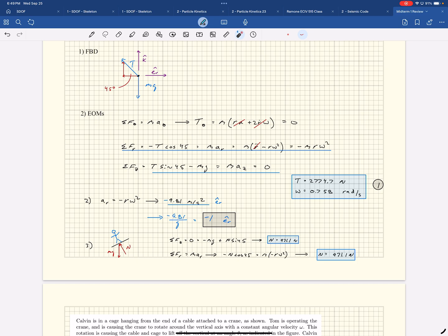We'll look afterwards. It is because of gravity. It's weird because gravity is an acceleration, right? But we don't really ever talk about it being an acceleration. We're putting it on the force side of the equation, so it's applying a force. So really, in this particular case, unless you let go of it and let it drop, it's not accelerating in that direction, and so saying that it has an acceleration of g down and it has acceleration to a_r is incorrect. Maybe you end up with the same answer, but it's not the same because it's not actually accelerating down with gravity. Does that make sense?